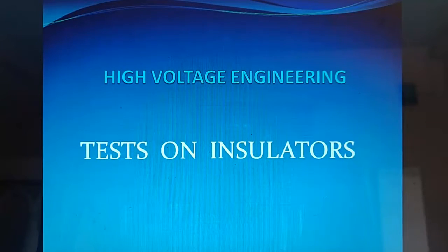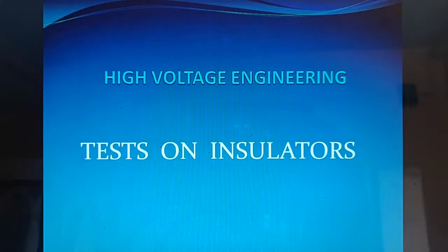Second, defective insulation material. If the material used in the insulator is defective anywhere, the insulator has a high chance of being punctured. Then, porosity in the insulation material. Here the porcelain insulator is manufactured at a low temperature.